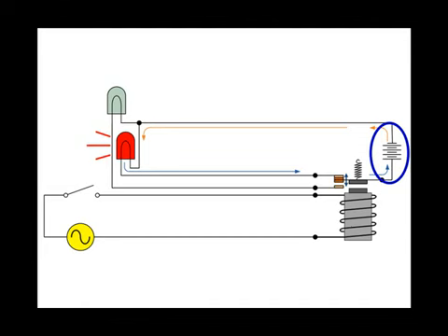The normal state for a relay is de-energized. Hence, the upper set of contacts are normally closed, and the lower set of contacts are normally open. With a single pole, single throw switch in the open position as shown here, the relay is in the normal state, and the normally closed contacts complete the circuit from the DC source of power to energize the load, which is a red indicator.